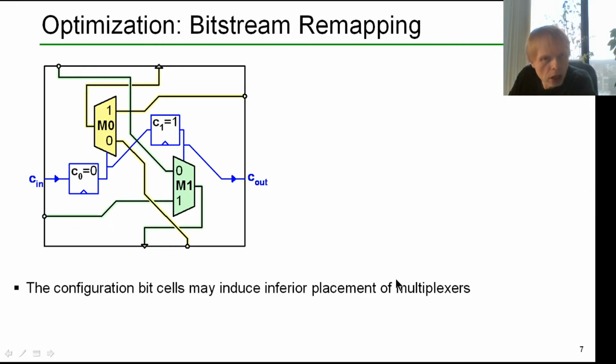Okay. The trick we applied is when we analyzed the final netlist and the congestion to see what we can do about it, we saw an effect that is shown here in this figure. If you connect your configuration latch or flip-flop to, let's say, a switch matrix multiplexer or a lookup table, that will create kind of a pull force.